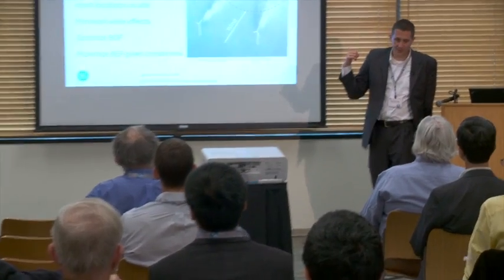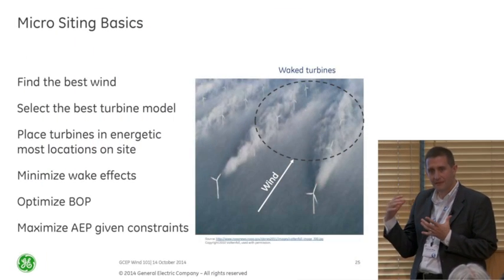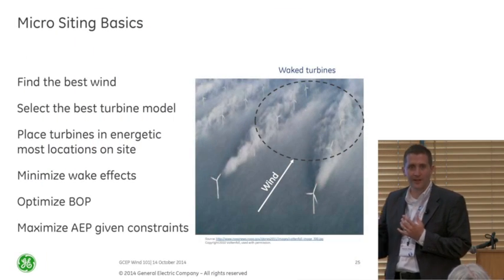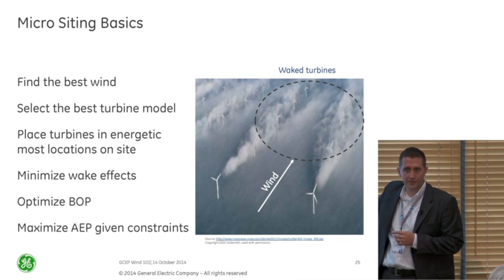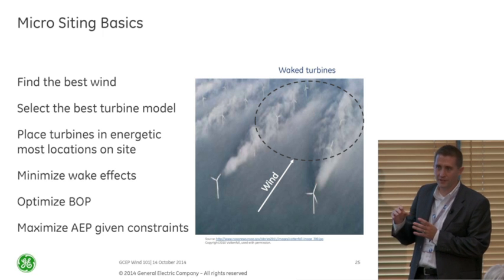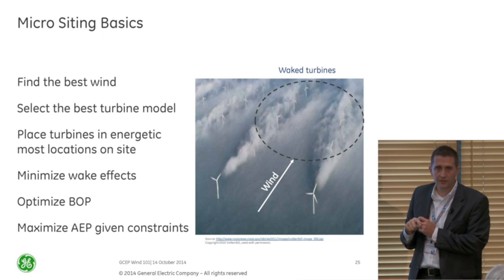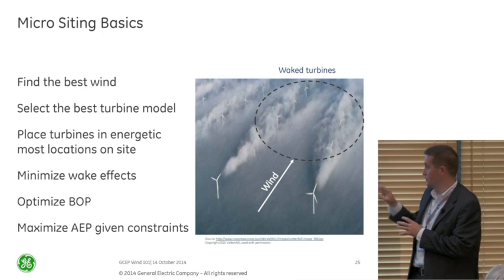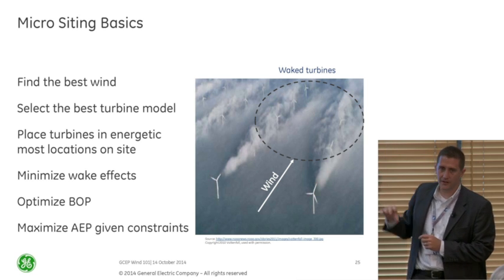All right, this is one of the most famous wind turbine pictures. This is an offshore turbine farm, and it happened early in the morning. You can see that there's fog generation happening, which really shows you what's going on in the wakes. And this is, I would say, relatively poor siting of turbines, right? So you can see that the predominant wind direction is the one turbines are being waked right into the other, and that's just aggregating into wake effect beyond that. So this is really a nice picture, which we typically can't see because the wind's nice and clear, but this is a nice picture of how these things propagate.